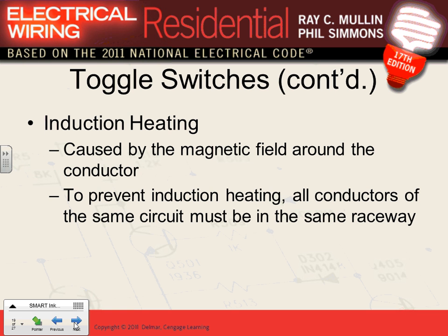We got that one. So if you are going to be creative like the classes before you, and you're doing 3- and 4-way switches in living rooms in the project, and I ask you how are you going to wire this, and you say, well, I take the neutral from this cable here, and the hot is coming in another cable there. Can you do that? No. If you're bringing the hot and the neutral, they have to be in the same cable. This comes up very commonly, guys, when you do 3-way and 4-way switch lighting.